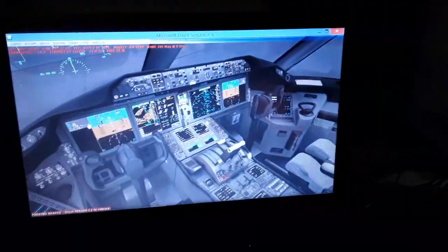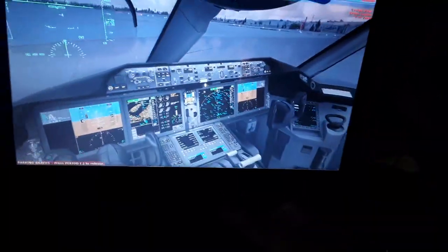Now I will show you the flight management computer over here, and how to create the flight plan. We'll input all the data we need for this flight. That includes the takeoff gross weight: the empty weight plus the passengers plus the cargo plus the fuel on board, where fuel is stored in the left and right wings. We have 30% in the left wing, 30% in the right wing, and 10% in the center tank.